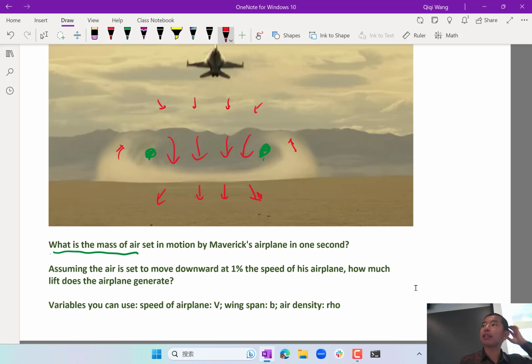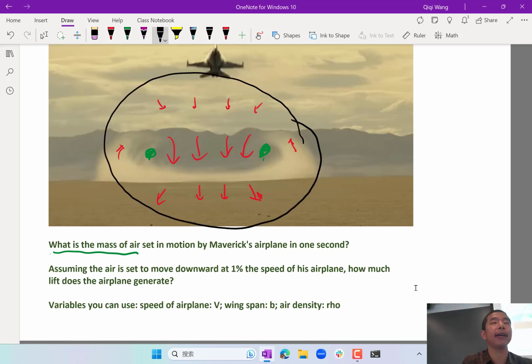So the area over which the flow has a significant velocity probably looks something like a circular or elliptical region. Both the height and width are some constant times the span-wise distance between the 2 vortices, which is roughly the span. So both the height and width of the air that's significantly moved by the airplane are proportional to the span. You don't need to use the chord.